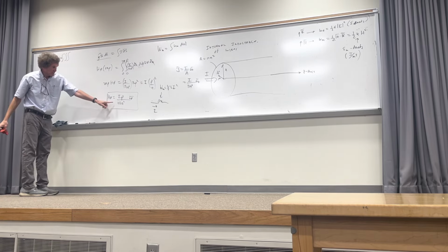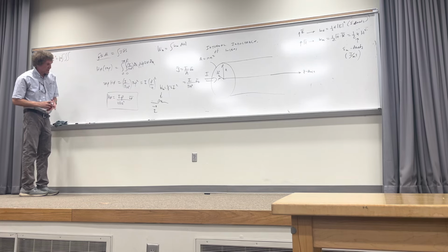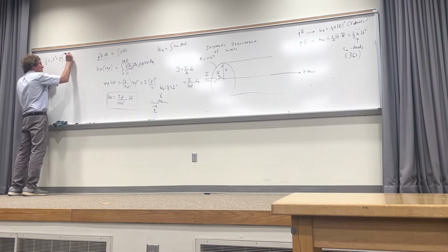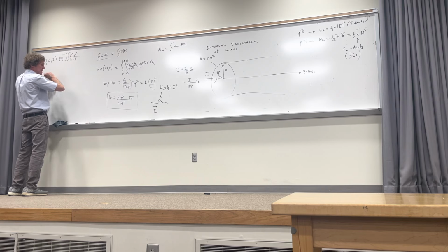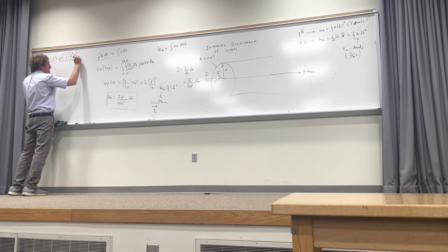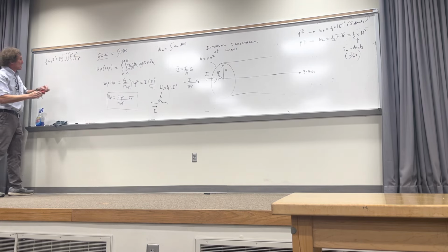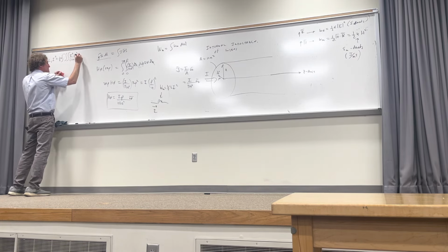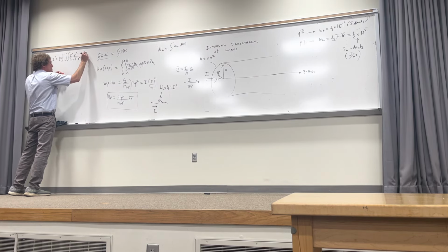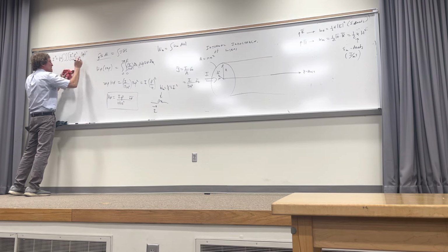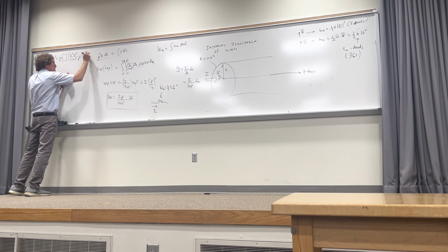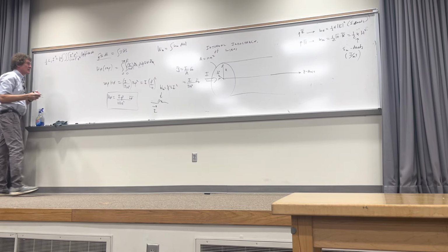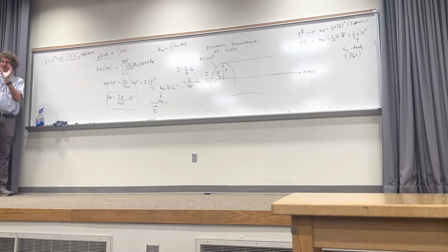Here's H, right? I've got a square. You'll notice I get I squared rho squared over 4 pi squared a to the 4th, right? Y'all see that? And it's going to be times the differential volume. Well, the differential volume would be equal to d rho times rho d phi times dz, and that's just differential volume in cylindrical coordinates.